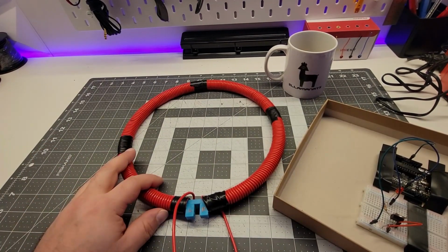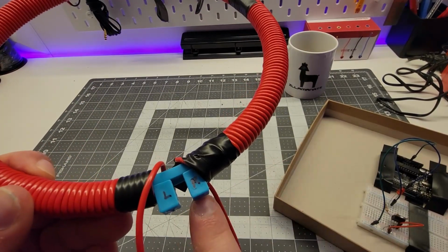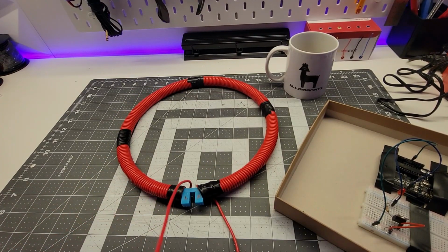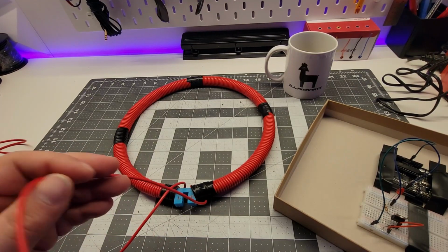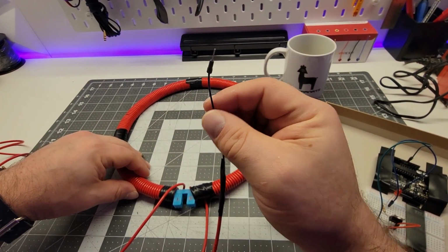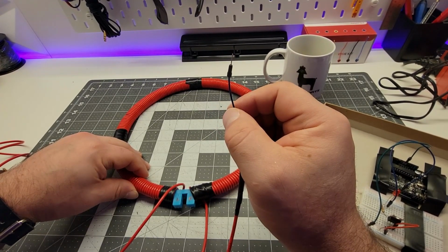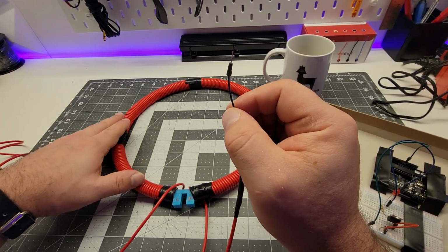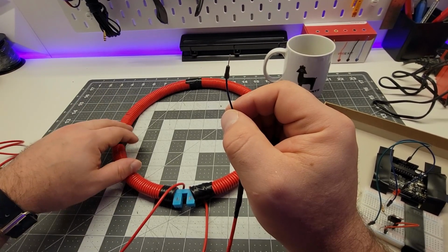This portion is actually very important. When we built the coil, if you remember, I marked off a left and a right. What you want to do is take your left and just put that over to the side, and take your right. And you need to get these in the proper places on the board. The left and right have to go into their correct slots on the board, or else the pulse going through the unit will not circle around the head in the correct direction, and it will negate the effects.